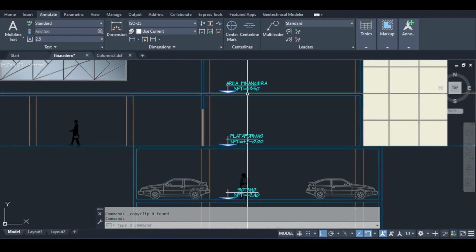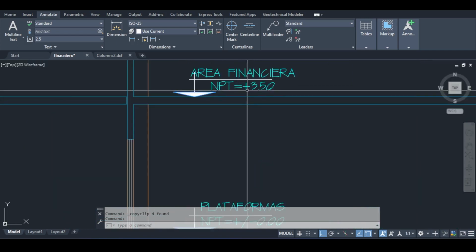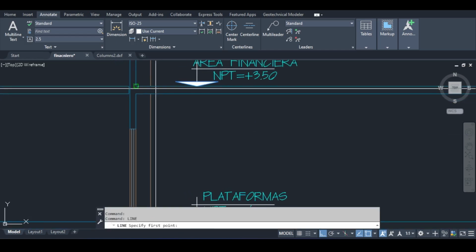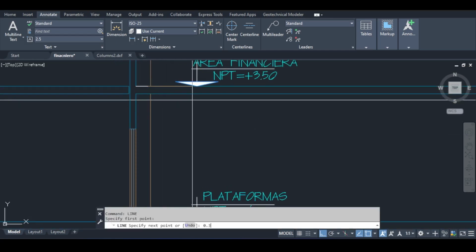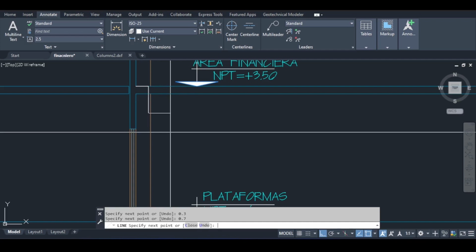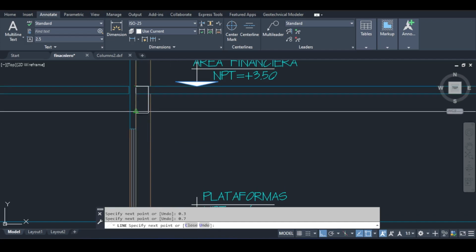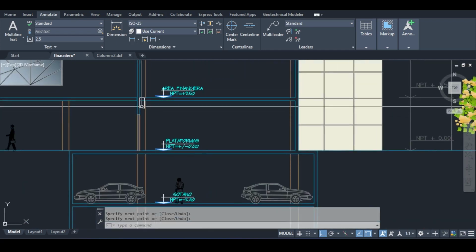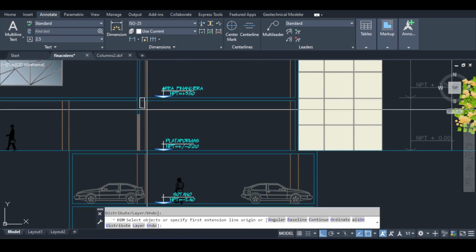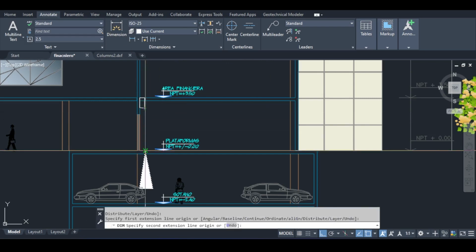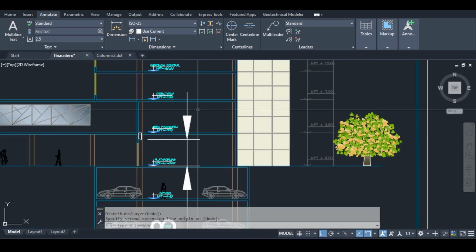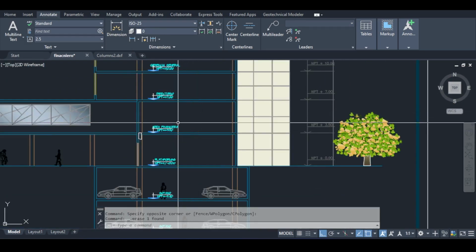The practical issue is that you have a height of a story. The height of the story is 3.5. If you add yourself a beam, and let's say that the beam is like, I don't know, 300, so 0.3 in this direction, and 0.7 in this direction. So this is your beam now, the white one. Okay, I know it's a little bit awkward. You see, when you define a beam with a certain height, you are taking away of the clear spacing of the story. Like the story had a spacing of 3.5, now it has a clear spacing of 2.8 because you took 700 millimeters away by using your beam.